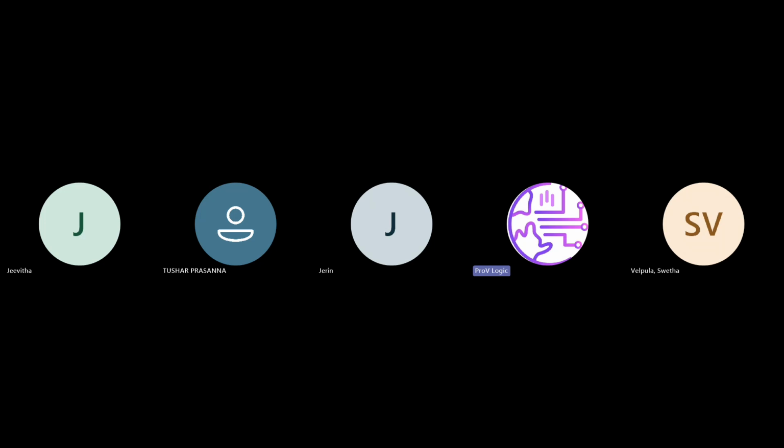So whenever you want to assign the input data to all the signals, every time you need to write data1 equal to $random, data2 equal to $random, data3 equal to $random, data4 equal to $random, data5 equal to $random. Like that, for every variable we need to assign $random. In that also, if you want to control, we have written for simple generating even, odd values and multiples of 3, multiples of 5 using $random, right?